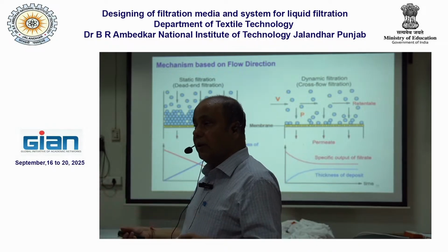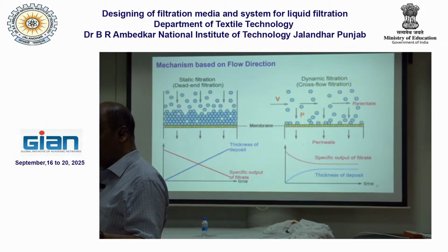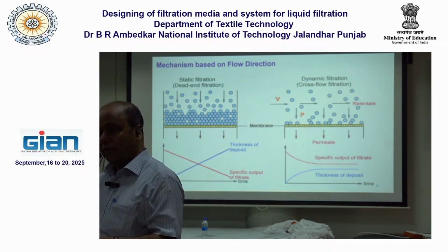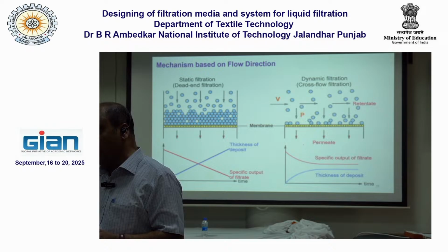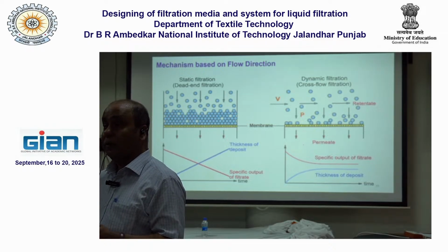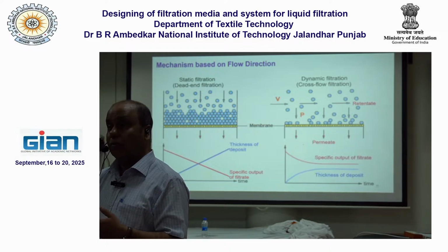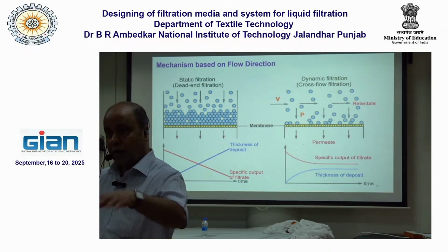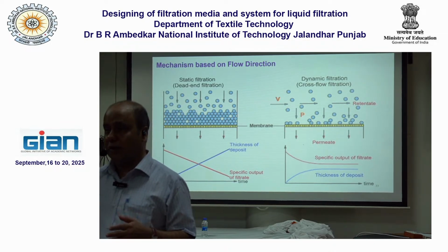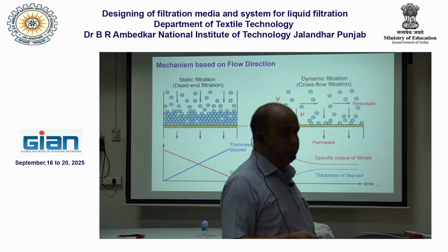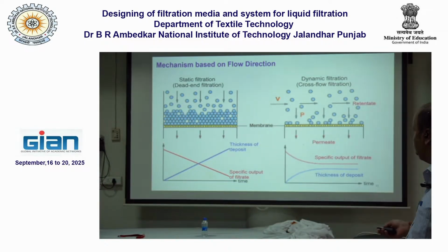Filtration is not a single step process. Initially you can have separation followed by filtration, so there could be a multi-step process. For example, you are using a filter press. In a typical setup you can have a filter press, and after the filter press you can also have ultrafiltration. It depends on where you will be using the water, whether the water will be reused or whether the water will be thrown out. So based on that, it is decided, based on the next phase of application.